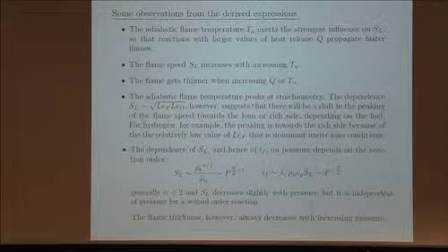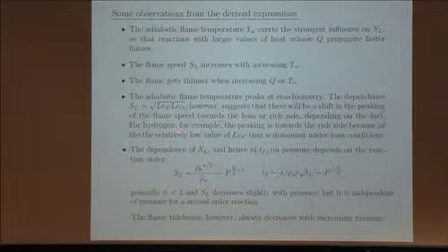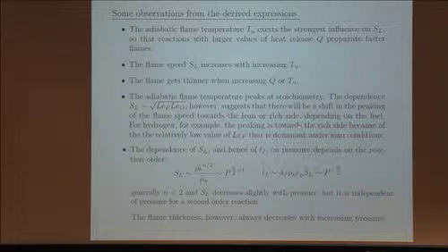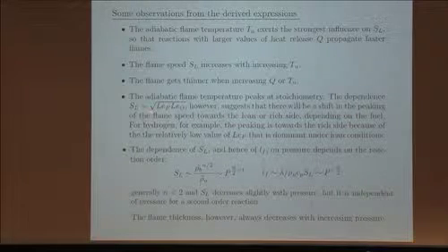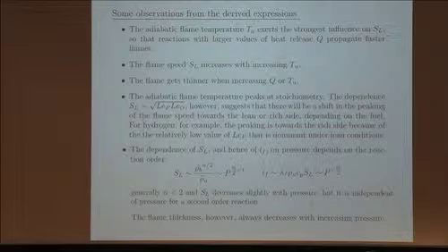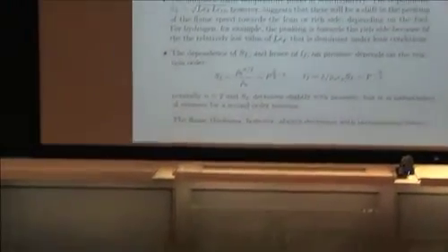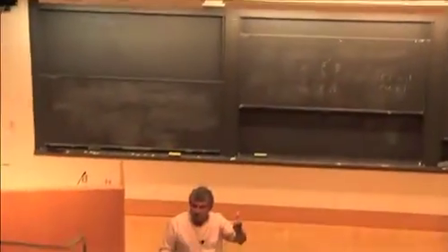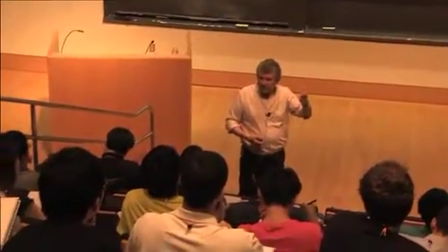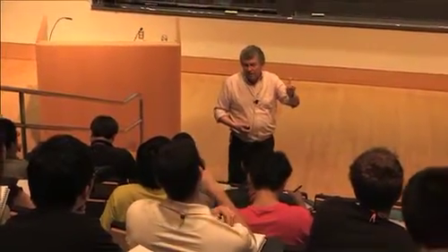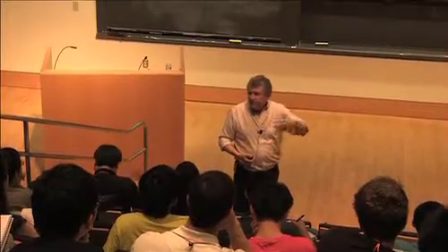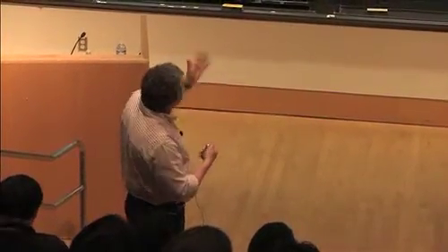So for example, as I will show you soon, for hydrogen, the peaking will be towards the rich side. Why? Because on the lean side, the more influential of the two is the Lewis number of the fuel, which is the deficient one, hydrogen, and hydrogen is a light fuel and has a larger diffusivity, and as a result of that, it will peak in that direction.